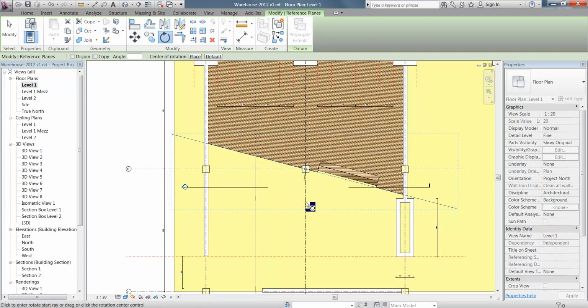And then you get another little gizmo, or this line that comes out from that icon. That's not the rotation angle, that's your base angle. So that means I can click onto this reference plane now, it'll start measuring from there. So I can bring it around now, and you can see finally the angle comes up, and that is the rotation angle. So I'm going to, by eye, just bring this down to the duct, and I can see pretty clearly how much of the duct I'll be covering as I move that, and that gives me some nice angle values that I can see. So what is it, 17, 18 or so, maybe even 20 might work.